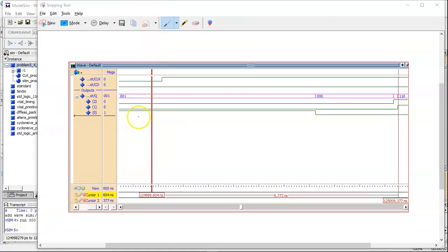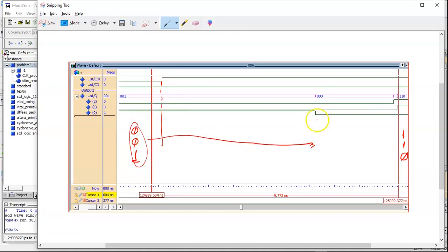Okay, now you see the code before the rising edge of the clock. You see the 0, 0, 1, and in the end it has to be 1, 1, 0, but in between you have the code 0, 0, 1, which is kept up to this point, and here one output is changing, the output 0 changes the value, so you have 0, 0, 0, and then you even have this other one which is 1, 0, 0, which is the 4, right?